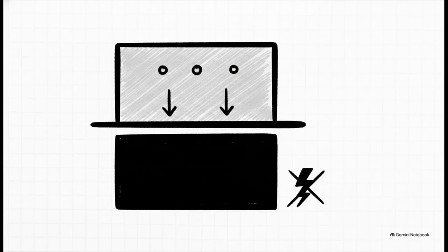But there is an incredible irony here. We just spent this whole explainer learning how we use solid-state diffusion to build the chip. But once the chip is built, diffusion becomes the ultimate enemy. Aluminum is specifically chosen for these interconnects because its diffusion rate in silicon is extremely low. If they used a metal that diffused easily at operating temperatures, the atoms from the pathways would slowly bleed into the silicon over time, ultimately short-circuiting and destroying the very chip we just built. Engineers literally have to choose materials to stop the diffusion process they just utilized.